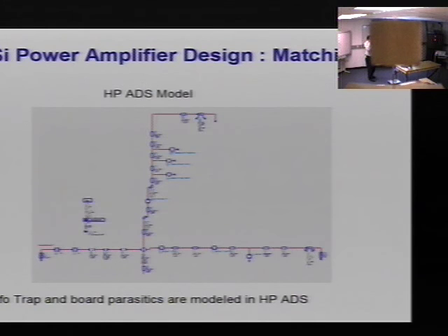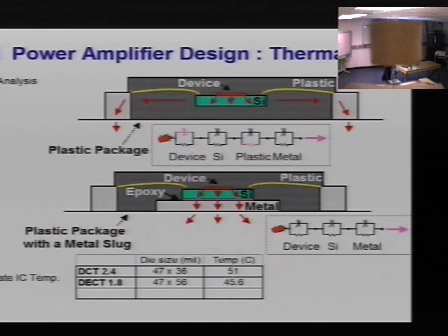But of course, getting a feed through of the third harmonics would be good, because that would square out a little bit of the waveform. And if you square out that waveform, then the overlap between the current and the voltage will be minimal at the collector node, and then you might have better efficiency. And since this is a nonlinear power amplifier, we like odd harmonics to go through. Don't like the even harmonics.